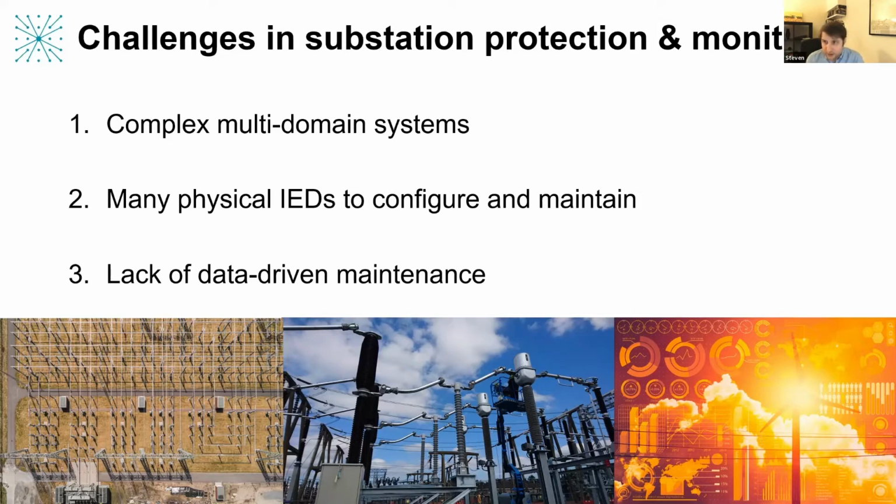The second challenge that I wanted to highlight is that utilities already have to manage many assets, particularly the primary assets, but also the secondary devices like the protection relays inside the substation. And in particular, for a digital substation approach, there's also this new type of device, which is the merging unit, and the process bus infrastructure that's needed to make that work and to deliver the measurements reliably.